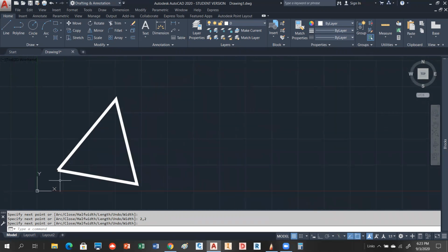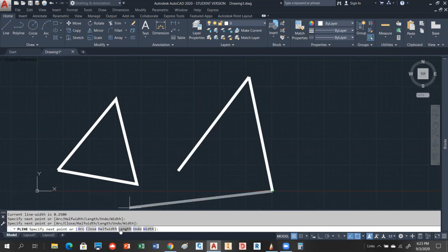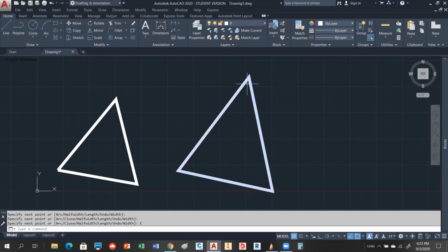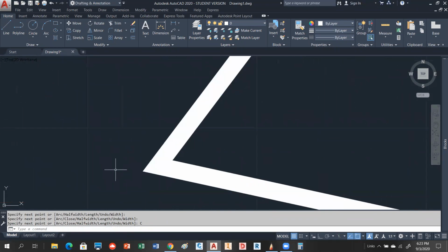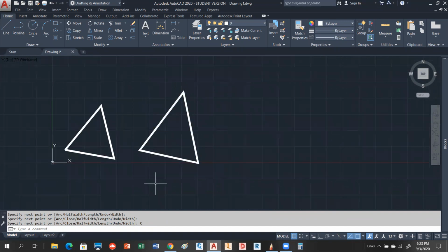So we're going to contrast that and show you what a closed polyline would look like. If I go into the polyline command and I just pick a point, pick a second point, pick a third point, notice down here now there's a close option. If you select that, notice it closes that polyline back and it beveled it shut, okay? So this polyline, if we listed it, it would tell me that it is open. This polyline is considered closed, okay? So there is a bit of a difference in the way AutoCAD looks at that. Did that work for everybody? Yep. Okay, great.